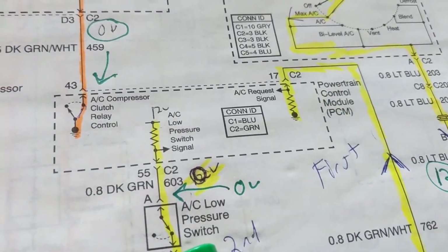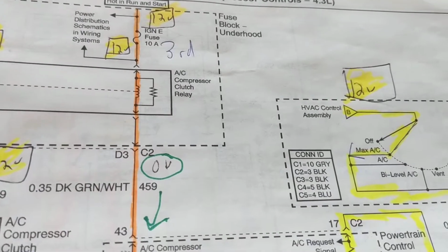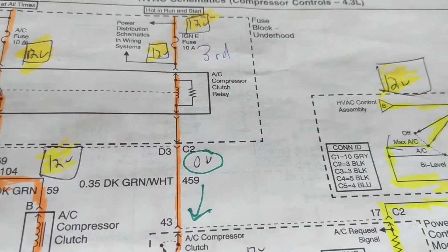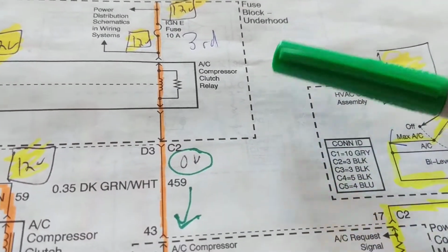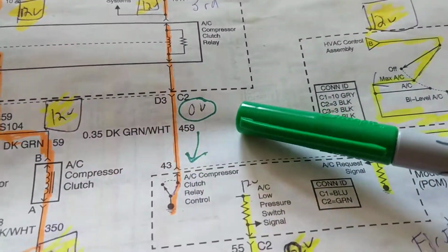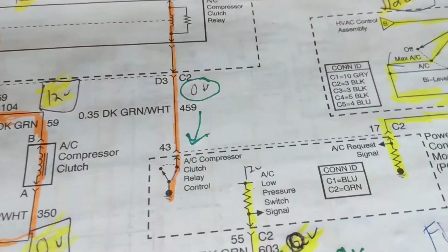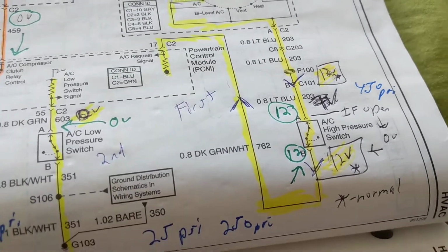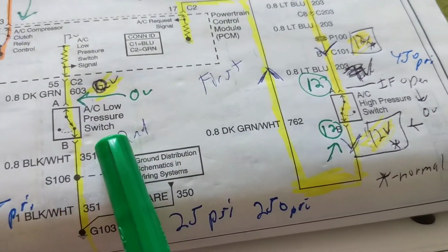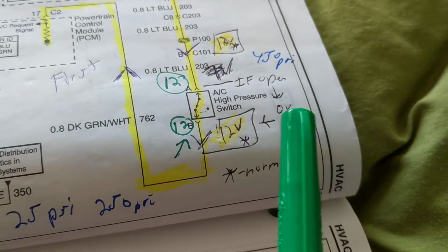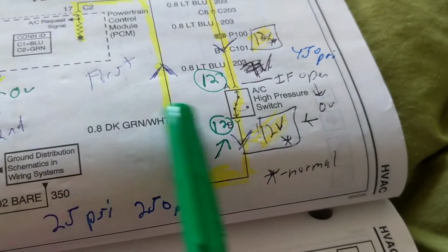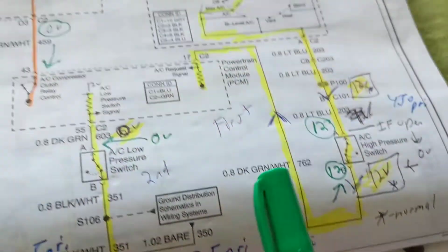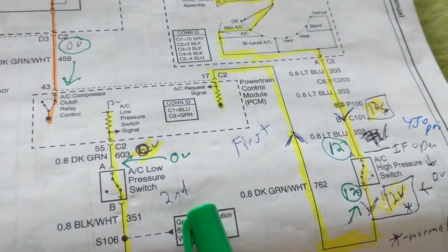This is like a fuse. Would you go and jump a fuse and say, let me see if the relay is working by jumping the fuse? No. This is a protection device. There's a reason why it's there. It's to protect the relay, to protect the clutch, to protect components from going bad. Therefore, I do not jump low pressure switches. I do not jump AC pressure. I do not jump high pressure. These are protective safety devices. What do I do? I measure voltages, and this is what I do.